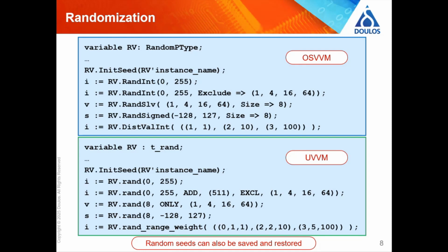That's not helpful. I want predictable pseudo-random stimulus so that every time I run it, I get the same thing. That's a bit counterintuitive because you're thinking, well, it's not random then, is it? Well, it was never random in the first place. It was pseudo-random. This is a computer, right? But the point is we do want it to be predictable unless we change something deliberately. If I want to change the stimulus, I will alter the constraints. I don't want the machine to do it without me.